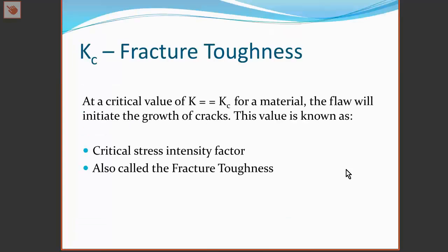Now, it has been found that when a stress is applied such that the value of K reaches a certain value, called the critical stress intensity value, which is known as the fracture toughness, the material will crack. So the flaw will open up into a crack under such conditions.